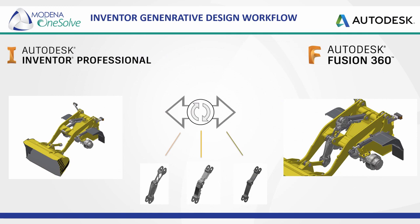Now that we have a better understanding of generative design and how it works inside of Fusion 360, we can take a closer look at how Inventor users will be able to leverage the benefits and capabilities of generative technology presented by Fusion. This workflow simply allows for Inventor files to be shared with Fusion 360 through a bidirectional link, either by importing or exporting data between the two applications or using the Fusion 360 desktop connector. The desktop connector allows Inventor and Fusion to access the same cloud storage location. It creates an associative link between the two files. A change made in Inventor will populate through to Fusion and vice versa.